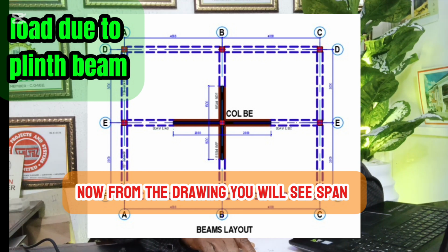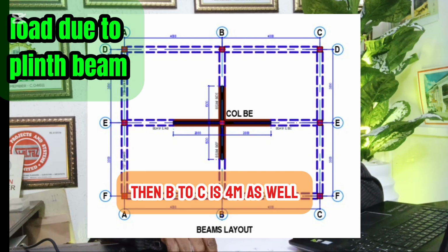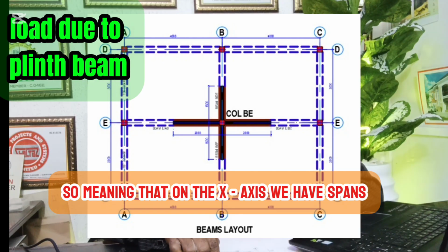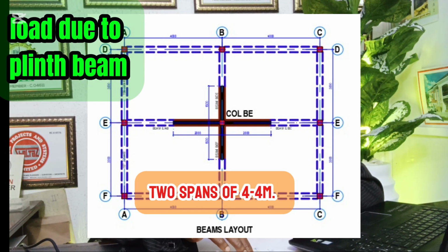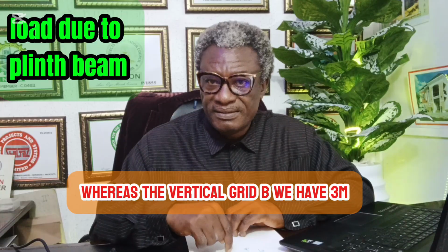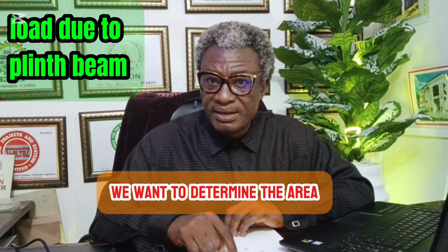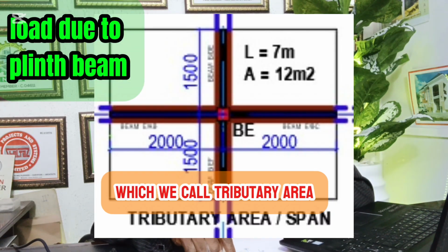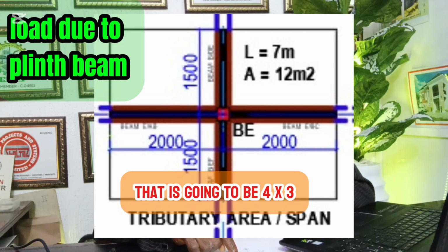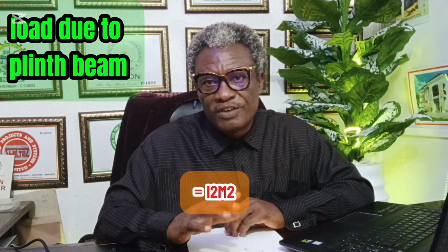Now from the drawing, you will see span AB, that is the distance from A to B, is 4 meters, then B to C is 4 meters as well. So on the x-axis, we have two spans of 4 meters, whereas on the vertical grid B, we have 3 meters, 3 meters. Now, before we start our calculation, we want to determine the area, which we call the tributary area. That is going to be 4 multiplied by 3, which is 12 meters squared.